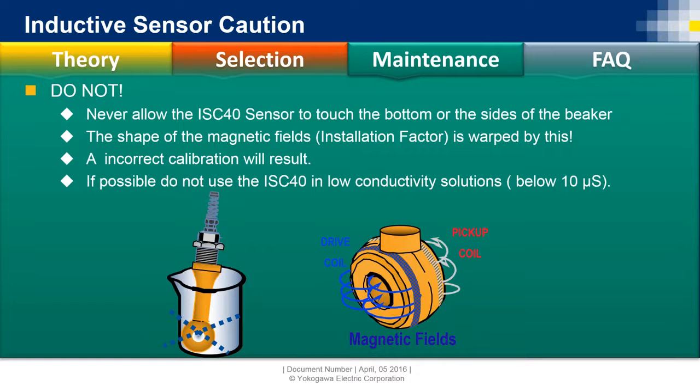You'll see that the same exact water sample will have a different conductivity reading. And this is because the glass beaker affects the magnetic field that the sensor generates. So you kind of constrict the magnetic field from the process that it flows through. So just be aware when you calibrate it that you have it where the field's not being bothered.